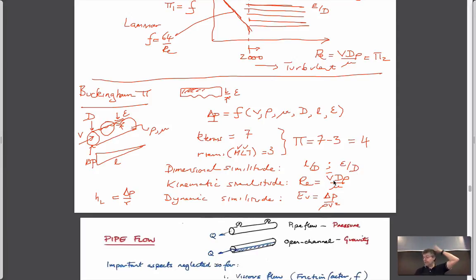And so we could go through Buckingham pi to get them, or you can also do it by inspection. If you can pull out numbers which satisfy the requirements of completely filling up the set of variables. We've used every single one of these parameters, hopefully. We've used pressure, velocity, density, viscosity, and all of the characteristic length dimensions. So we've satisfied the requirement that within these 4 non-dimensional parameters, we've used up all of the parameters which describe our system. So we're honoring our system.